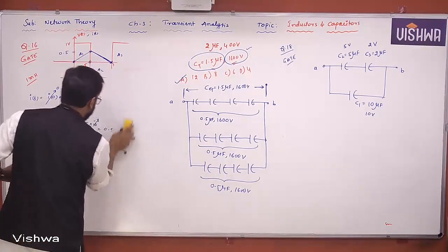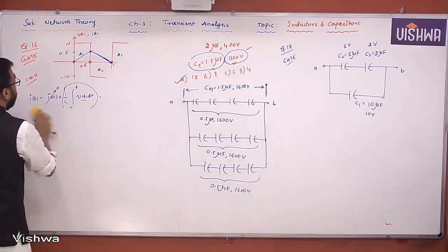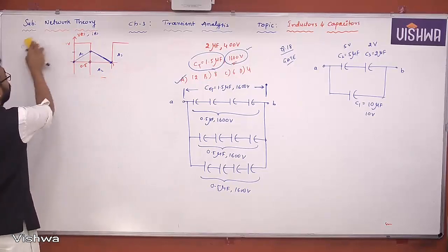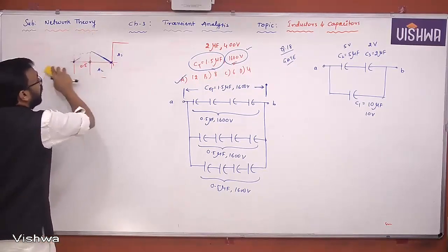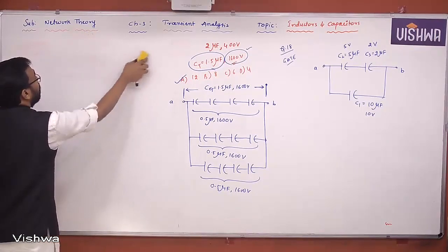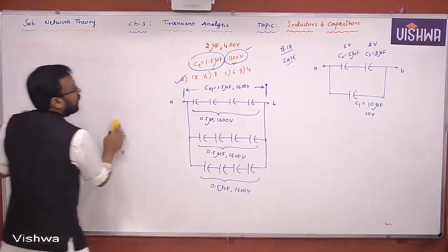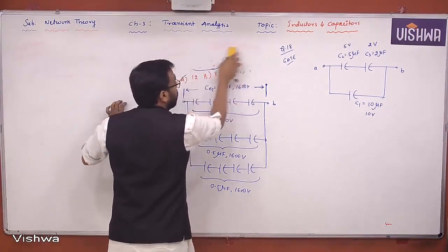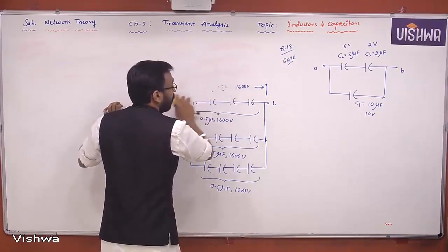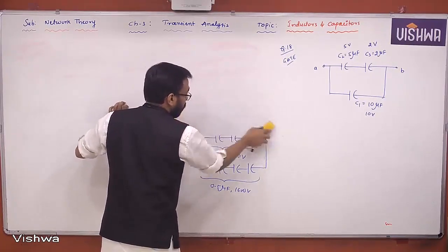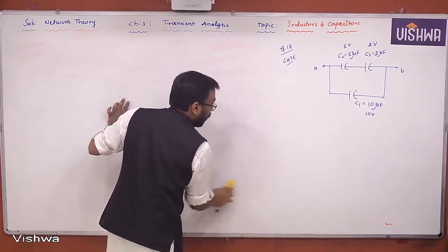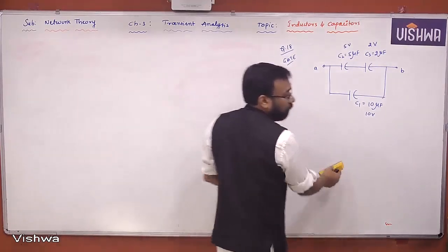You know that when the voltage increases, the stress on the dielectric will increase, and if that voltage hits the maximum dielectric strength of the capacitor, then the capacitor will be damaged. Yes or no, all of you? The dielectric gets punctured and finally the capacitor gets damaged. So let us see now what is the maximum safe voltage that can be applied.